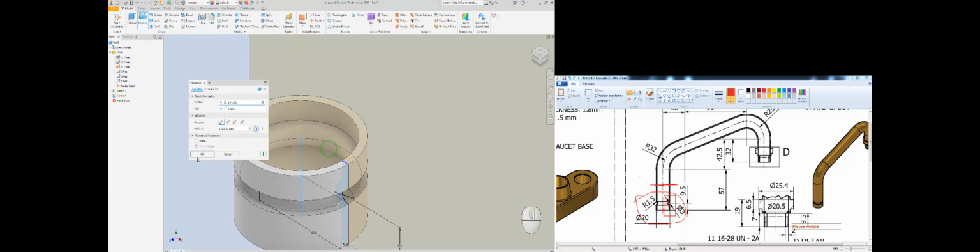As I have told you before, the length here is not important. We will just divide as we wish to have these two profiles. This is the profile which we have created. I will finish my sketch and take the revolve tool, and if I have a closed profile and a rotation axis defined as center line, Inventor just gets the whole profile here. Also, I have slits on the outside which are 1.5 millimeters.